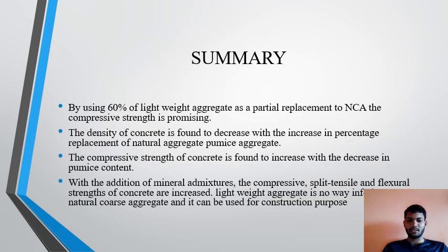After that, summary: with 60% lightweight aggregate as partial replacement of NCA, the compressive strength is promising. The density of the concrete is found to decrease with the increasing percentage replacement of normal aggregate by pumice aggregate. The compressive strength of the concrete is found to increase with the decrease in pumice content. With the addition of material mixture, the compressive, split tensile and flexural strength of the concrete are increased. Lightweight aggregate is naturally inflated coarse aggregate, and it can be used for construction purposes. Thank you.